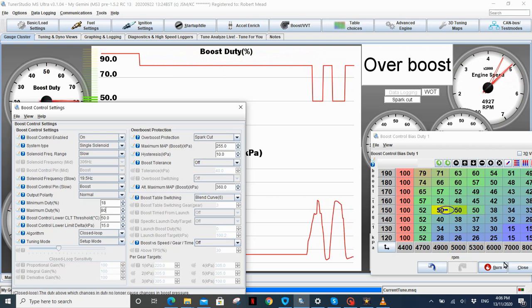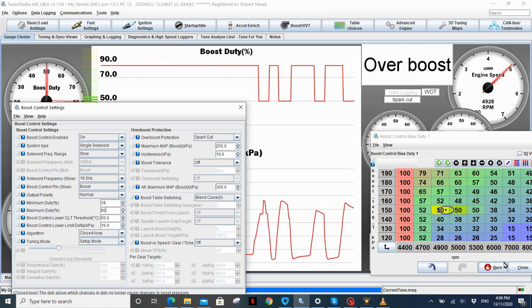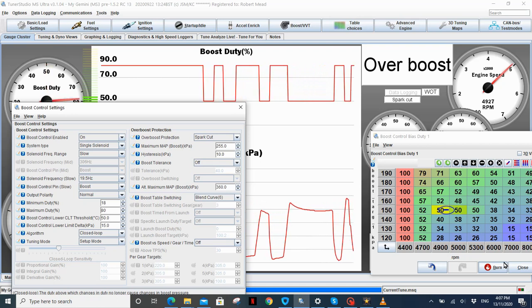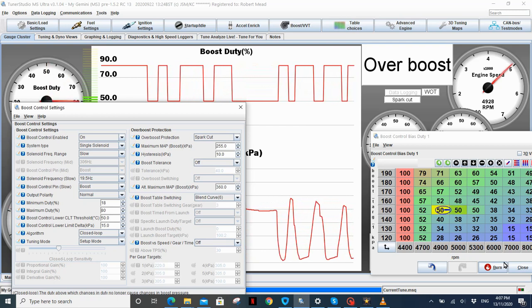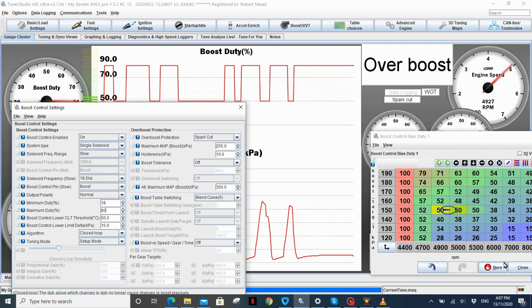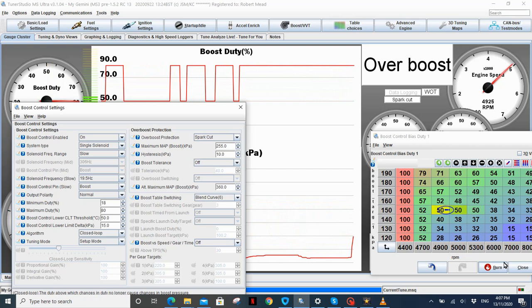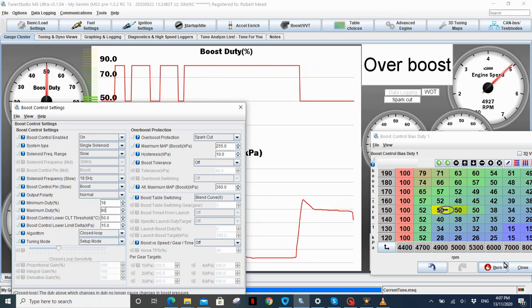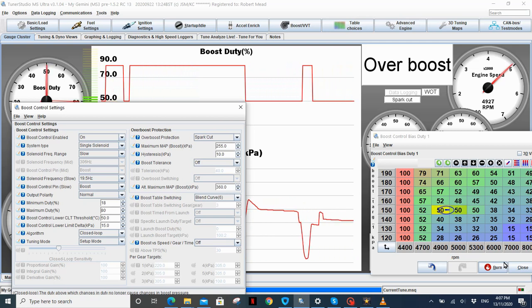Now this is what it will do in all the closed loop modes, and that's why this is the bias table, because it sets up what you want it to do. So we're putting in a bit of not intelligence, but a bit of pre-known knowledge, so stuff we've worked out either by setting it up in this mode, or if you previously ran in open loop, then you should be able to have a look at that table and transcribe over to this table to see what it should be running, and you should be able to fill in that table. So we'll just have a bit of a play around here. We've got to get it up and then we've got to change the RPM.